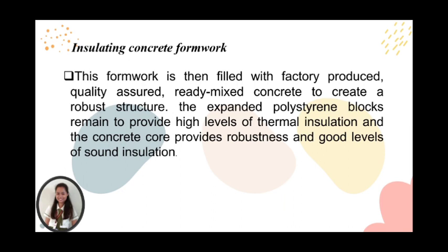The design and thickness of the overall construction depends on the properties required for the wall and the structural requirements for the in-situ concrete wall, including steel reinforcement if necessary. A variety of shapes and components exist permitting the construction of different building forms, including curves. The exterior of the building can be clad in any finish and internally is either dry-lined or plastered.